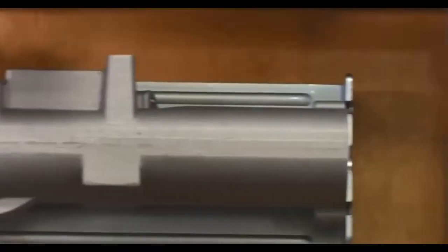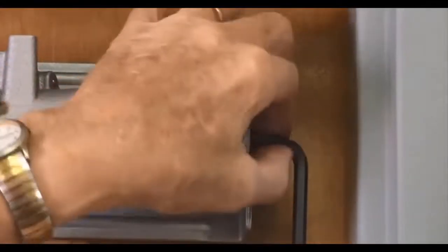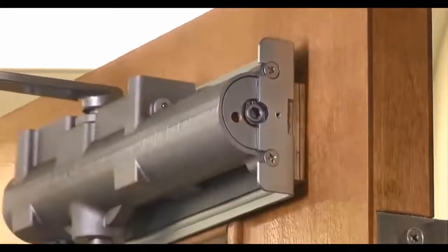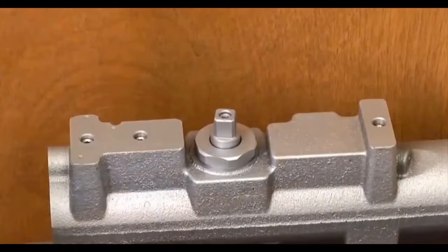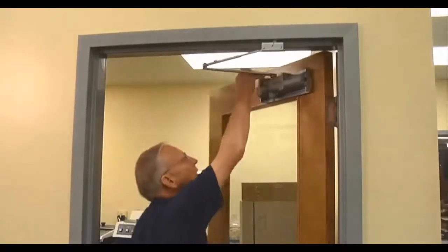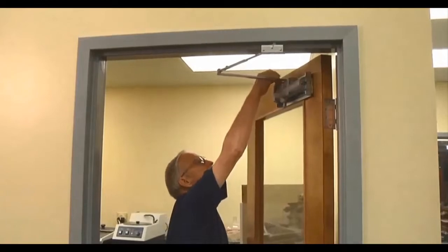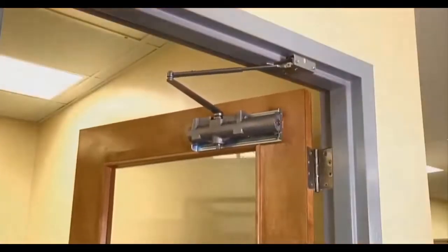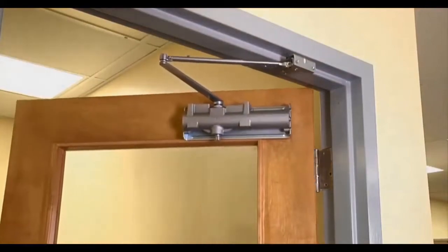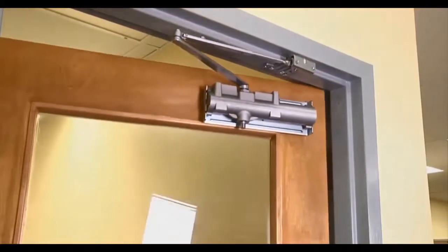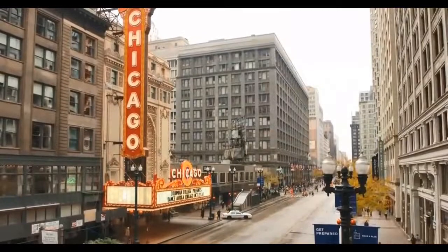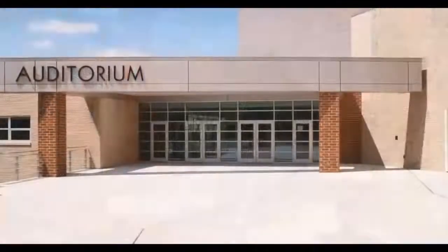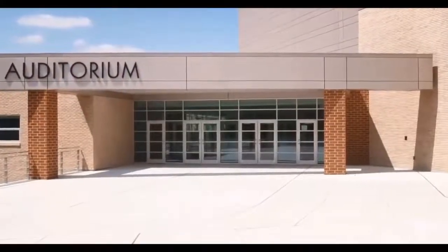The spring adjust screw may be adjusted to obtain the appropriate closing force and to accommodate for varied door sizes and latching hardware. Our cast iron closers have easily accessible valves for adjusting back check, sweep, and latch speed functions. During the closing motion, internal pressures seldom exceed 50 psi, but some doors are located in high abuse situations. Examples might be a city high-rise on a windy day, or school doors that children constantly force to close.